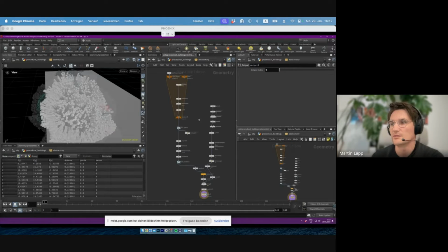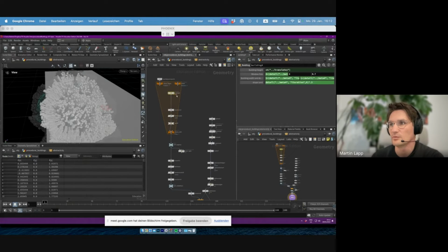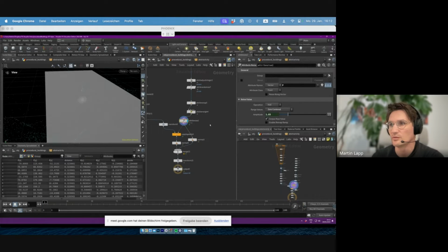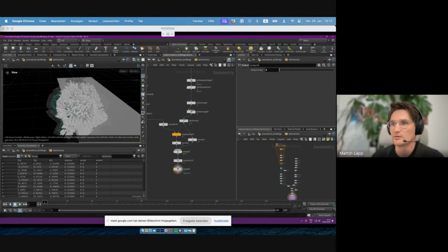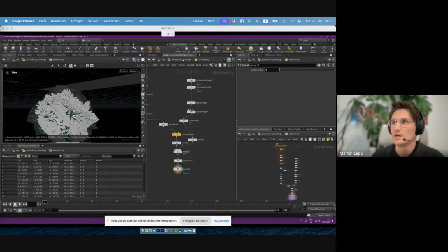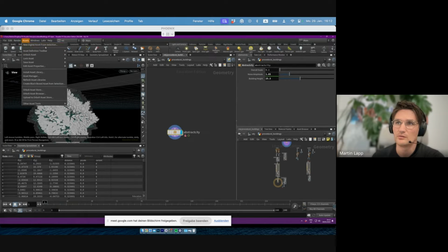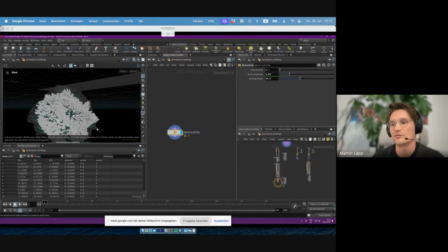It's exactly the same as we discussed before, the building in a for each loop, and then it's copied onto this noised up sphere, and this then gets generated here. I created an HDA out of this by just selecting it and going to Assets, New Digital Asset from Selection, and that lets me save that as an HDA.